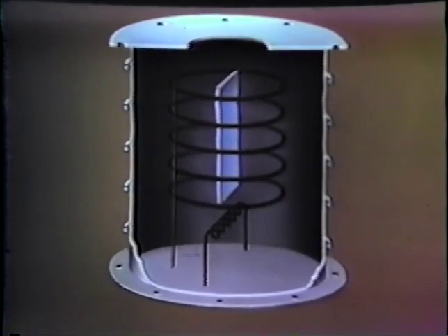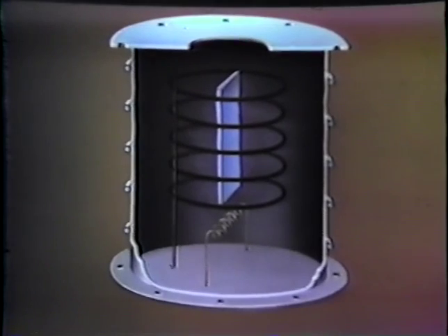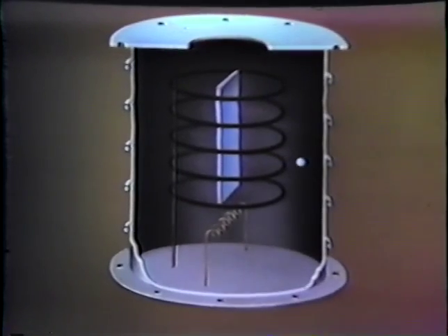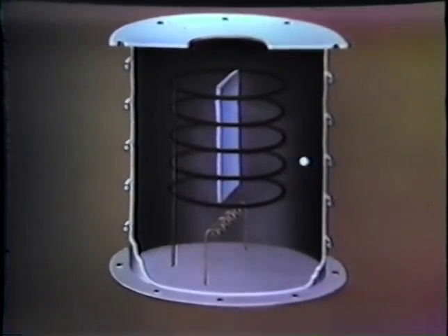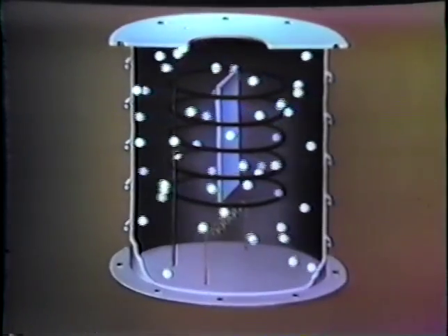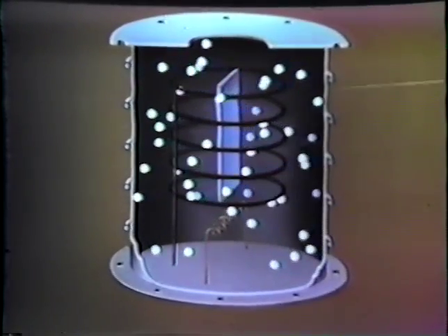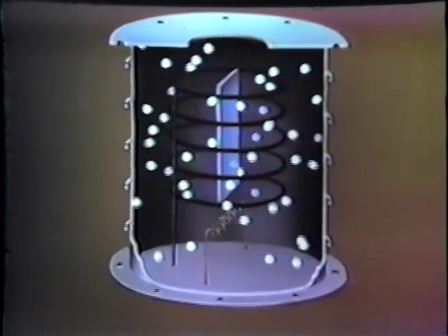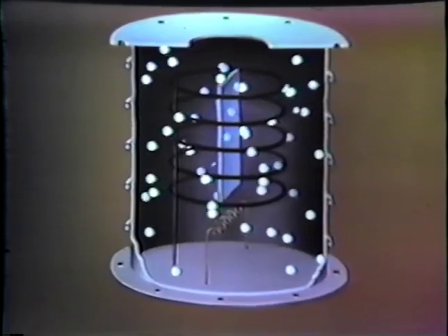In the evaporating type of getter ion pump, cathode bombardment causes the titanium to evaporate. Here we see one such atom as it travels toward the cooled wall, where it combines with a gas molecule. Oxides, nitrides, hydrides, and other more complex combinations result in stable compounds, thus removing the gases from the pump chamber, as well as from any chamber or volume connected to it.